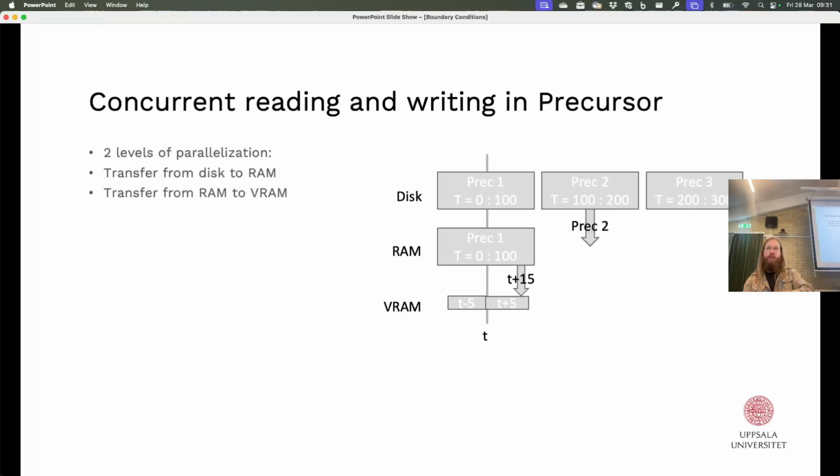So we only have the two time steps that we need for linear interpolation right now. The boundary condition actually takes very little space on the GPU. And then we're concurrently loading the next one that we will need. That way, we never have to wait. We do memory transfer hiding, so we never have to wait for it. And that actually makes this the fastest boundary condition in LBM besides the periodic boundary condition.